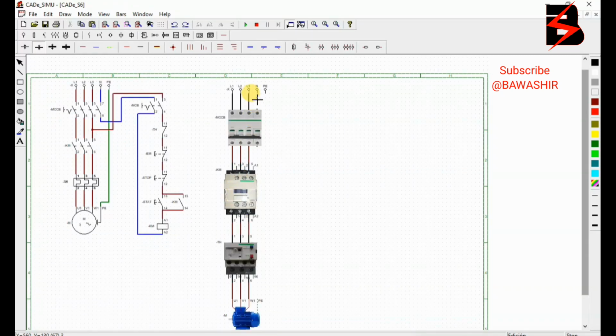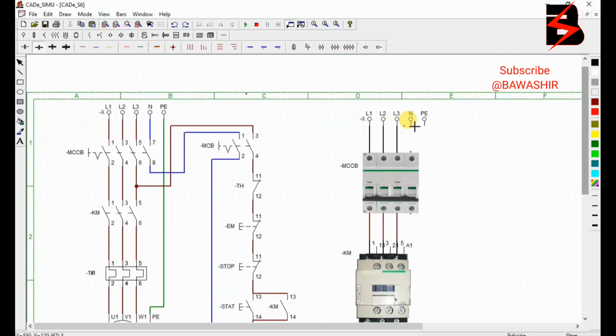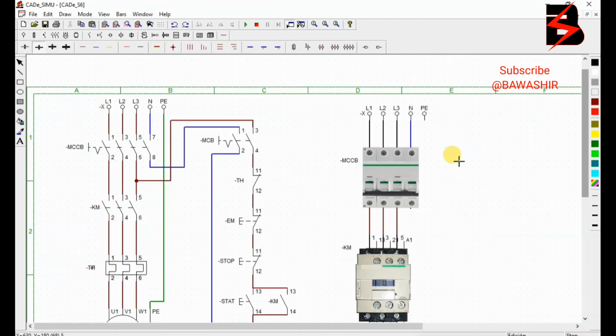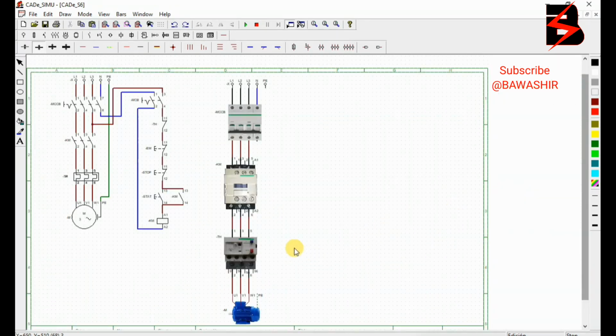With the neutral, actually let me connect earthing. I shall take it direct. Then neutral shall only stop in the breaker. We shall need it when we want to wire the control circuit. So that is it. I think we are now done with the power line. We can go to control.